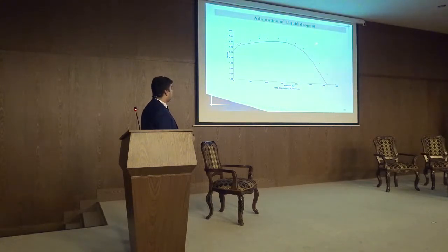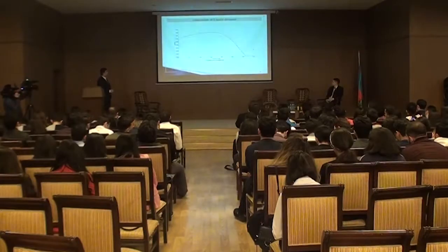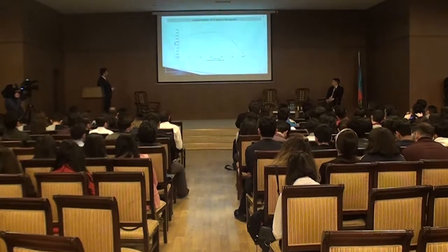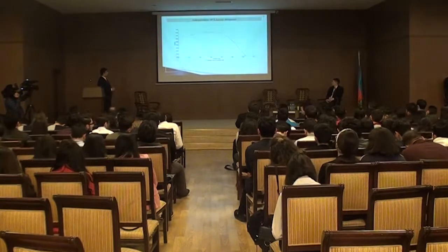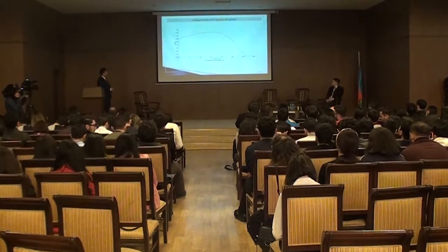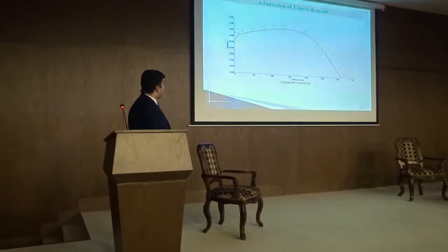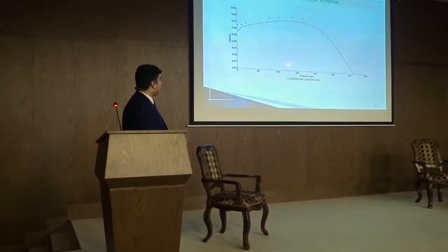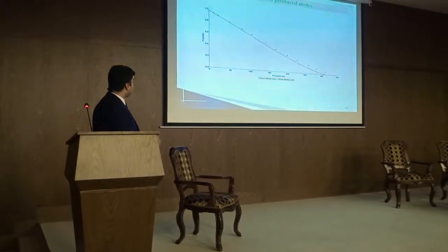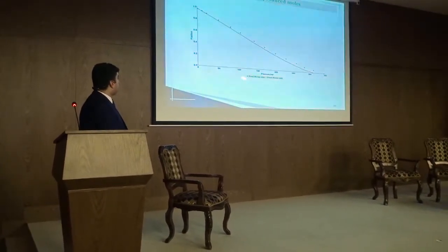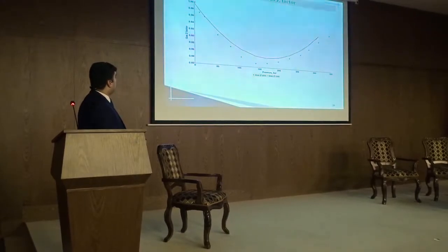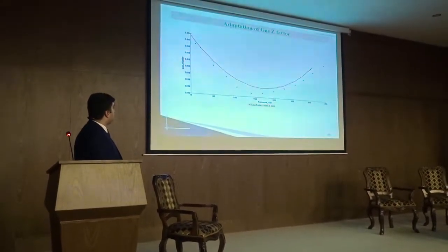And this is the adaptation or matching of liquid dropout. These dots illustrate real data, and this is what we adapted by changing some properties related to liquid dropout. And it is for produced moles and gas Z factor.